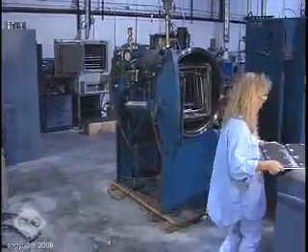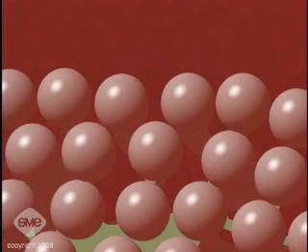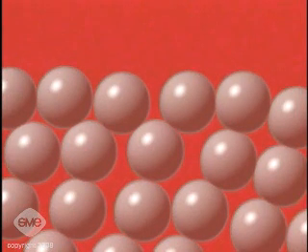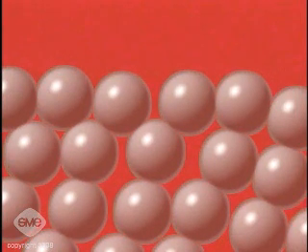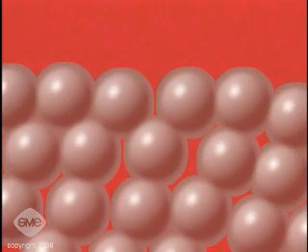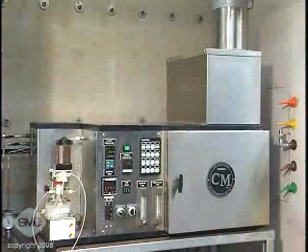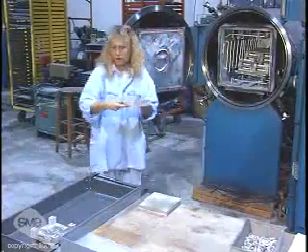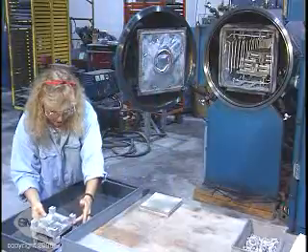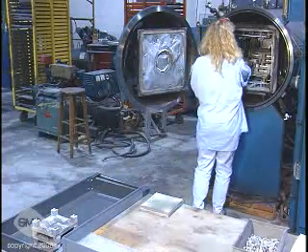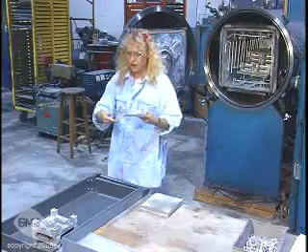Sintering follows in a two-stage furnace. In the first stage, the remaining binder is removed at an elevated temperature. In the second stage, the part is sintered. During sintering, the part shrinks, removing almost all of the porosity. Total time for debinding and sintering can range from 8 to 24 hours or more. However, identical parts can be processed simultaneously, increasing overall production rate.